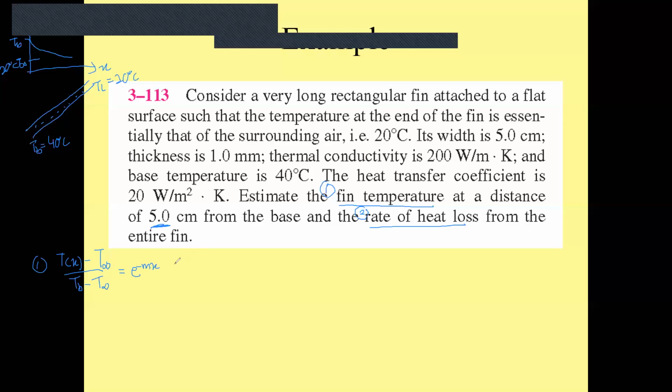So you have to solve this. These two temperatures are known, and x is 5 centimeters, because you want to know the temperature at distance x. And then m. How do you find m? m is given by the square root of hP over kAc. h is given here, the heat transfer coefficient.